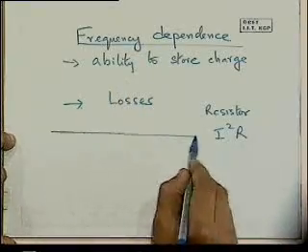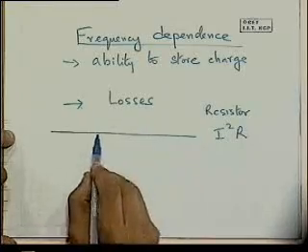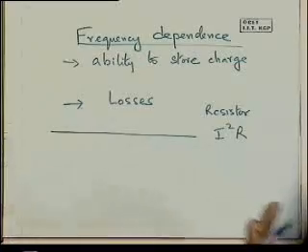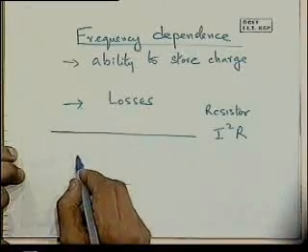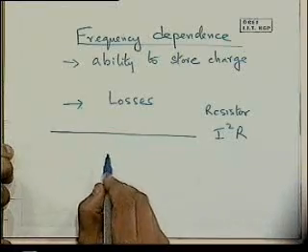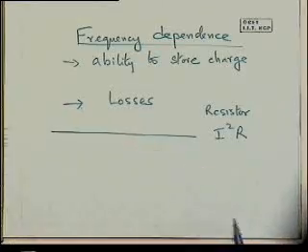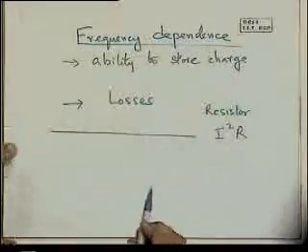Now, as I mentioned earlier, capacitors, these dielectrics, not only store charge, in addition they are able to serve as an insulator between conductors. And in that sense, there's going to be some critical field above which they will break down. Okay? They simply cannot indefinitely sustain any field that is applied across them. All media will ultimately break down. And a classic phenomenon that we see is lightning, where the air is breaking down and we have a conducting path from the clouds to the ground. Similarly, any material has got a breakdown field, and there's some critical value that it can sustain.